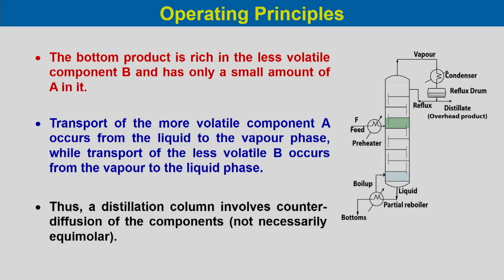Thus, a distillation column involves counter diffusion of the components, not necessarily equimolar. Distillation involves counter diffusion of the components, and it may not be equimolar counter diffusion, because the heavier or less volatile component is transferred from the vapor phase to the liquid phase, and the more volatile component is transferred from the liquid phase to the vapor phase in the distillation process. That is why it is a counter diffusion of the components.